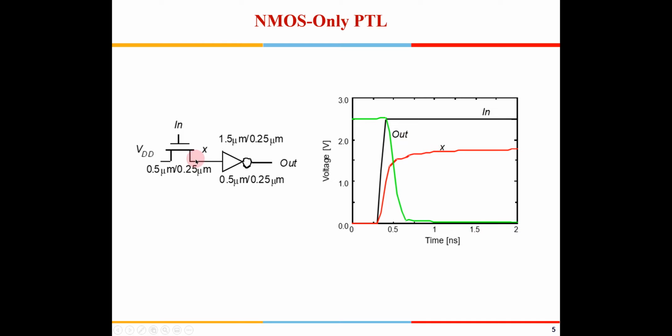See, whenever we use an NMOS as a switch out here, you will find this X is what is shown out here, right? So for 0 it will be 0. For 1 it will not be full VDD. Okay, so to restore the final level, after several pass transistor logics are implemented, in the final stage you might want to have an inverter to restore the levels back to VDD, right?